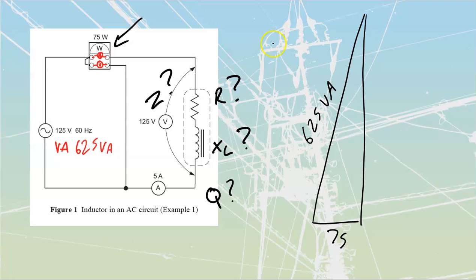Let's start by figuring out what we have got for our resistance off of this one. R is equal to I squared divided by W. Oops, sorry, upside down. W divided by I squared. I'm working off the wrong one. I should do W is equal to I squared R. What we're going to isolate for is the R, so we're going to divide the I squared across to this side. Moves it out of that side. So we have R is equal to my watts divided by I squared.